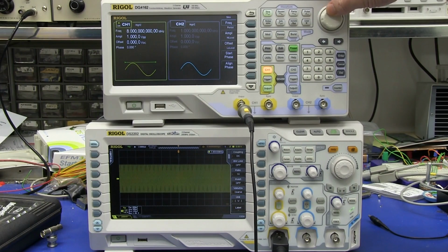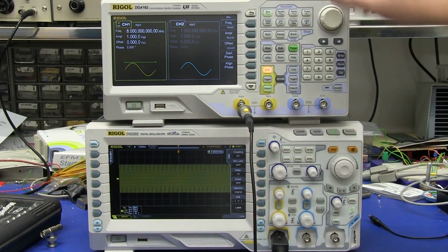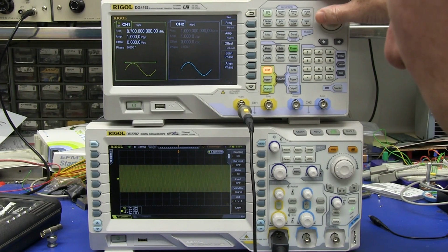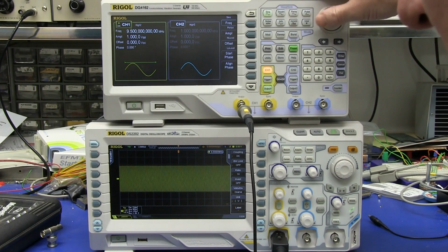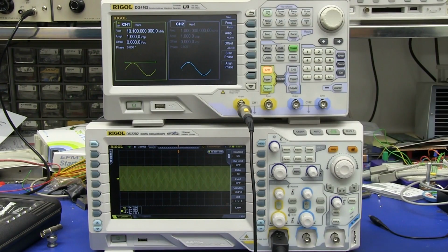Let's see what we get at 8 megahertz. There we go. We're getting 800 millivolts. So it's actually, bandwidth is better than what it says on the data sheet. And 707. Let's go down. Probably can't read there. There we go. That's practically 0.707, 10.1 megahertz bandwidth of this probe on ×1 mode.